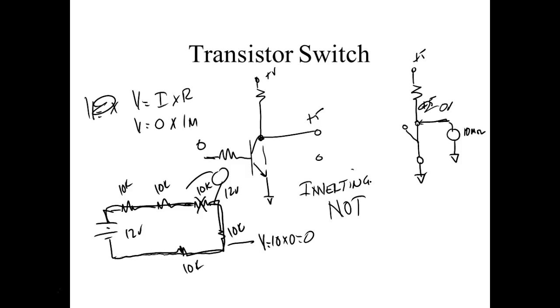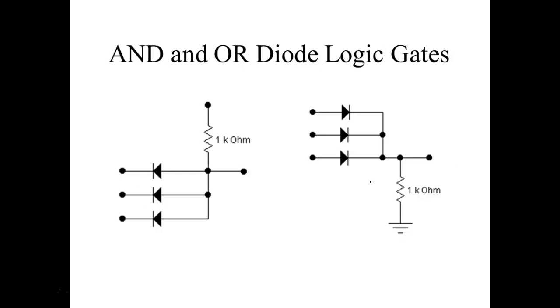So I could take this transistor and put a transistor right here. I can use that resistor right there. Yeah. I can put a transistor right there. And now this becomes an AND. But I can't call it that, because this guy inverts, right? So what a NAND is, it says all highs give me a low. An AND says all highs give me a high.